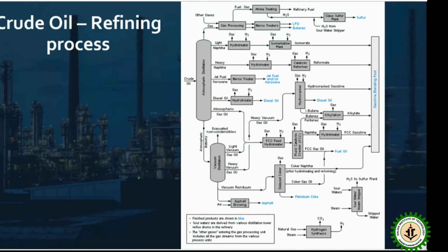Sir, mainly corrosive liquids enter into the tube side, and why? Because the shell is very costly, and to protect it. Very good. So shells are protected. Tubes can be plugged if they are corroded. Okay. But the question is, if both are not corrosive liquids, you have to design a heat exchanger, so where does the inlet go?